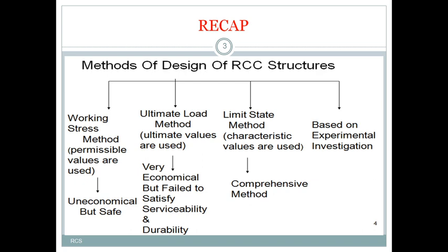The elements designed by using this method give very thin sections. A thin section may bend or deflect. Because of its thin section it may deform, and because of that it is unstable. I can say it will give an unstable structure. Because of a thinner section the usage of material and manpower will be less, so it may be very economical, right?